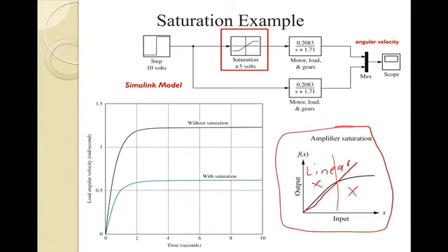One of the things we want to do is use Simulink graphically here. Let's do a step input of 10 volts, so 0 to 10 volts here. In our system, we want to do two things. We first want to ask, what's the impact here? Let's look at this branch right here.